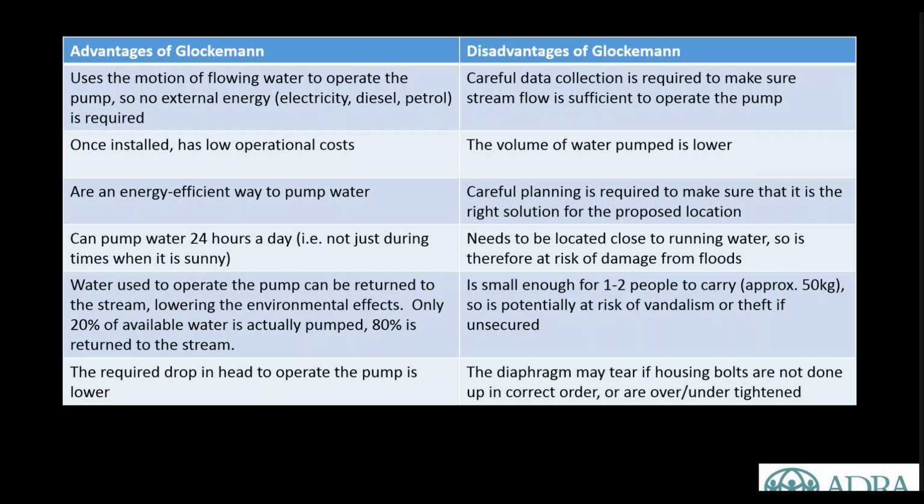It obviously needs to be located close to running water, so is therefore at risk from damaging floods. And the other thing we did actually find was a bit of an issue is that it is quite a small pump. It's only about 50 kilograms and therefore is at risk of theft or vandalism if left unsecured. And the diaphragm might actually tear, and I'll show you a photo in a little while, if the housing bolts are not done up correctly or are over or under tightened.